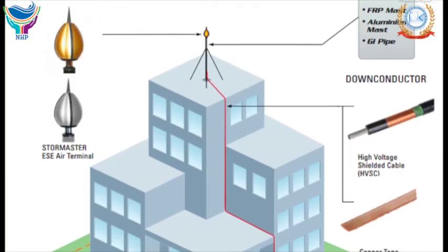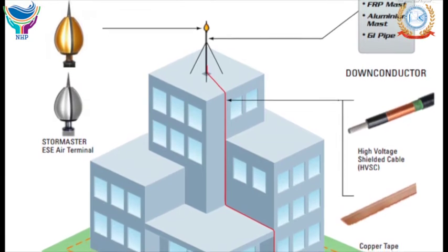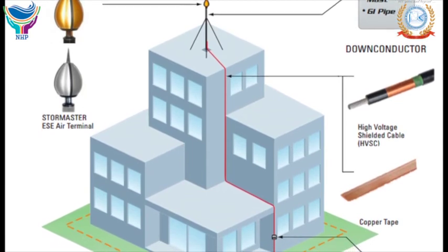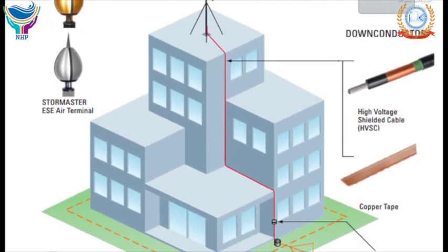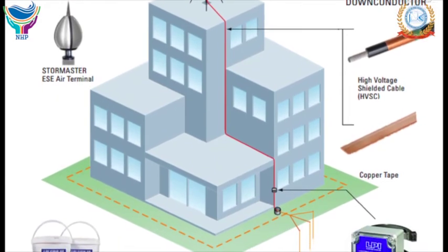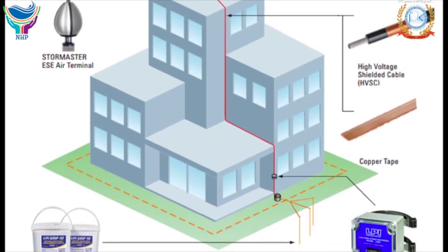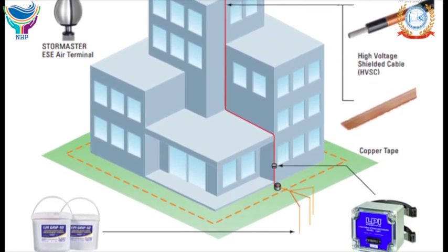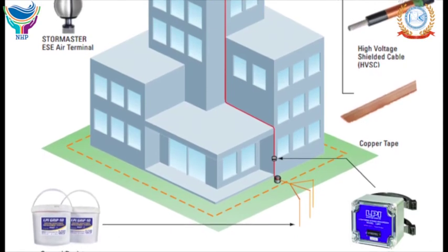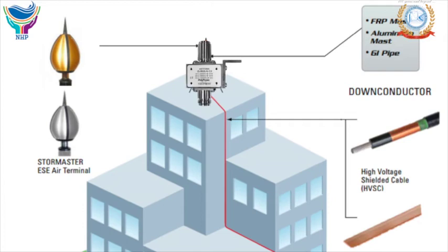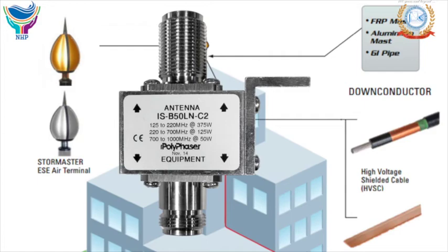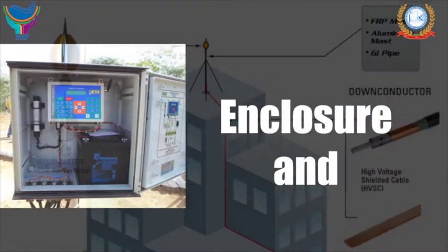Lightning protection. Each station shall employ a grounding system that will protect the electronic equipment from electrical surges caused by lightning. The system will consist of a single point grounding system which will tie all grounding wires to a copper grounding plate. The plate will then be connected with a copper grounding strap to a grounding rod. Antenna cables will utilize polyphasers to protect the DCP from lightning damage.